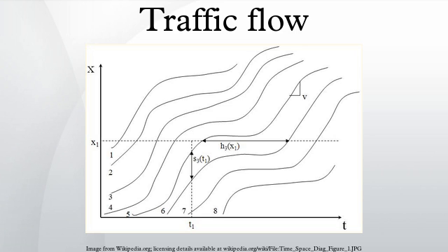Time delay. Both user optimum and system optimum can be subdivided into two categories on the basis of the approach of time delay taken for their solution: predictive time delay and reactive time delay. Predictive time delay is based on the concept that the system or the user knows when the congestion point is reached, or when the delay of the freeway would be equal to the delay on city streets, and the decision